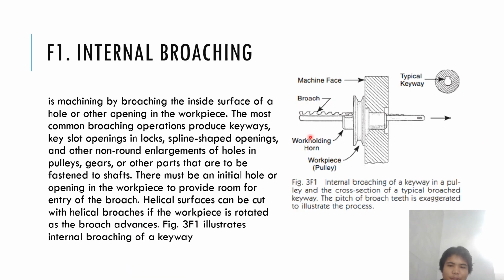Internal broaching is machining by broaching the inside surface of a hole or other opening in the workpiece. The most common broaching operation produces keyways, key slot openings, spline-shaped openings, and other non-round enlargements of holes in pulleys, gears, or other parts that are to be fastened to shafts. So you can see here, this is the broach, this is the existing hole, and it's cut by the broach. Look at the teeth of the cutter: it starts smaller, and the last one gets bigger.